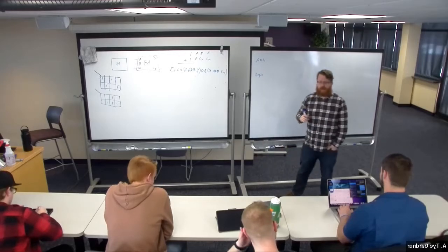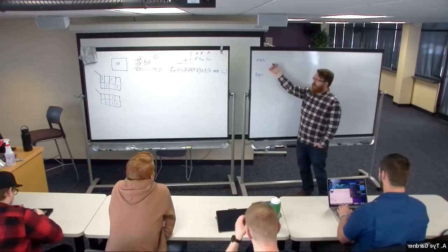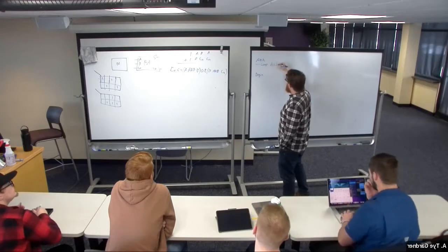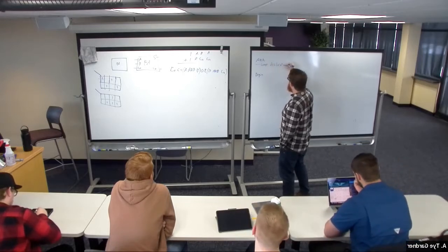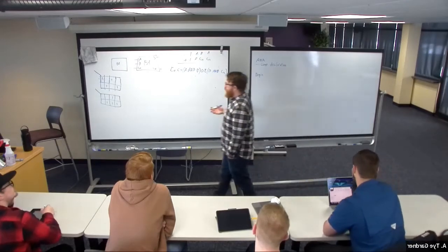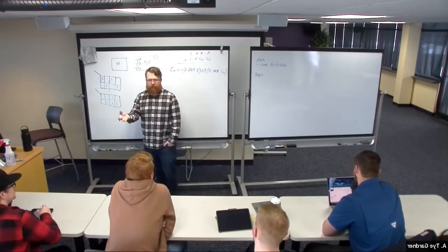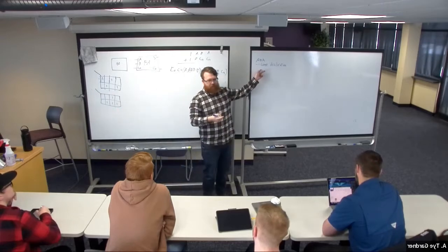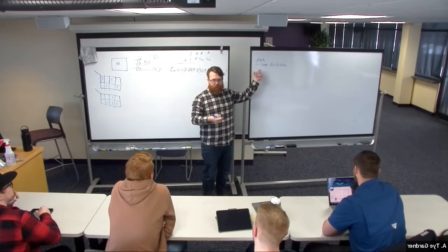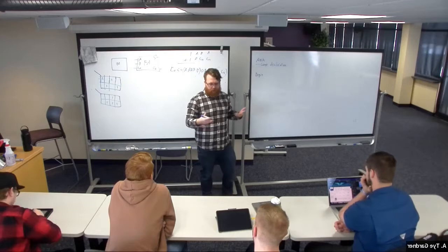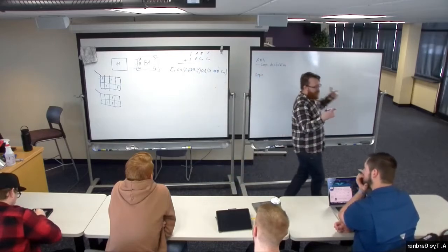and its begin, right? This is where we say things exist. So here is my component declaration. The component declaration, again, the way to do this, always, always, always, is just go to your entity, which is its own design file, right? You copy the entity, you paste it over here, and you change the word entity to component and change the word end from end entity to end component, right? We're just adding component in 2 places, and that copy and paste says this exists.